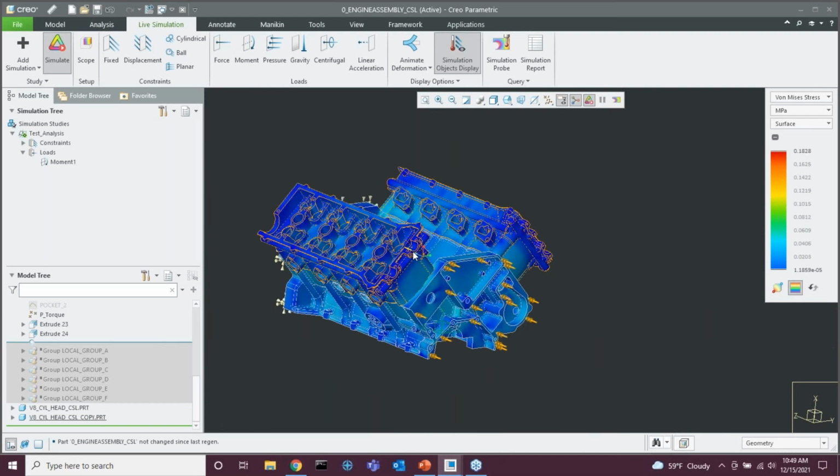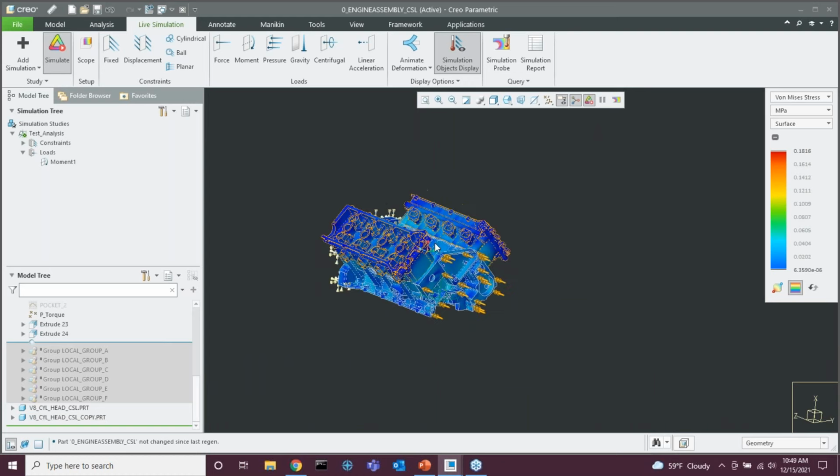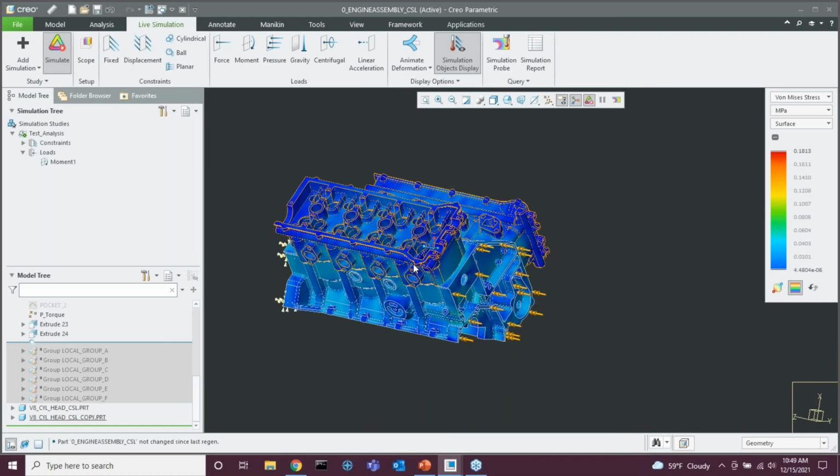And that is what Creo Simulation Live strives to be. You, as a designer, are able to make quick design changes, such as those cutouts, and see what the results look like. You can get trends of data and start to see which of your changes actually helps the overall structural, modal, or thermal performance, and get those results very quickly. But these wouldn't be numbers you would want to report out to a design review. These do have inaccuracies compared to the actual data that a true CPU-based FEA solver like Creo Simulate or Creo ANSYS Simulation would provide.